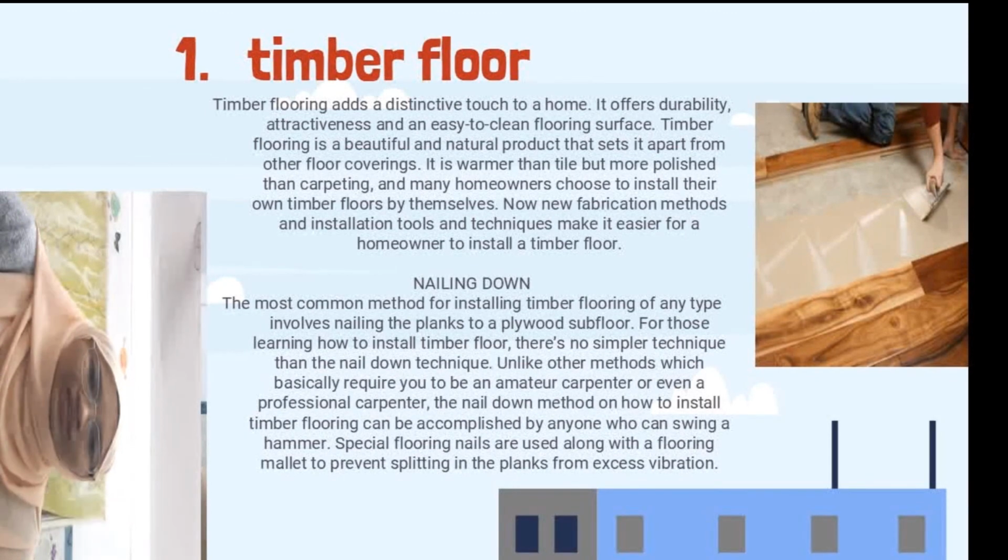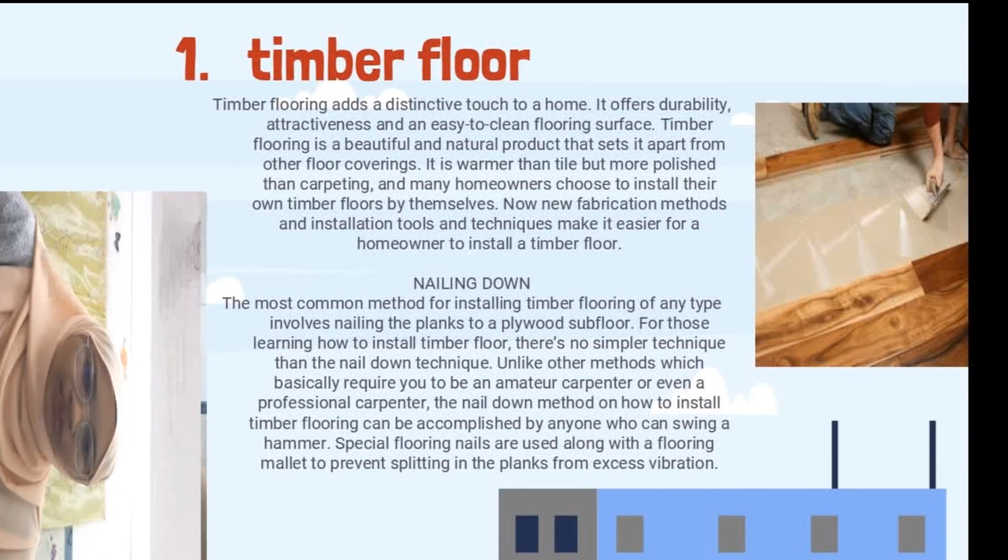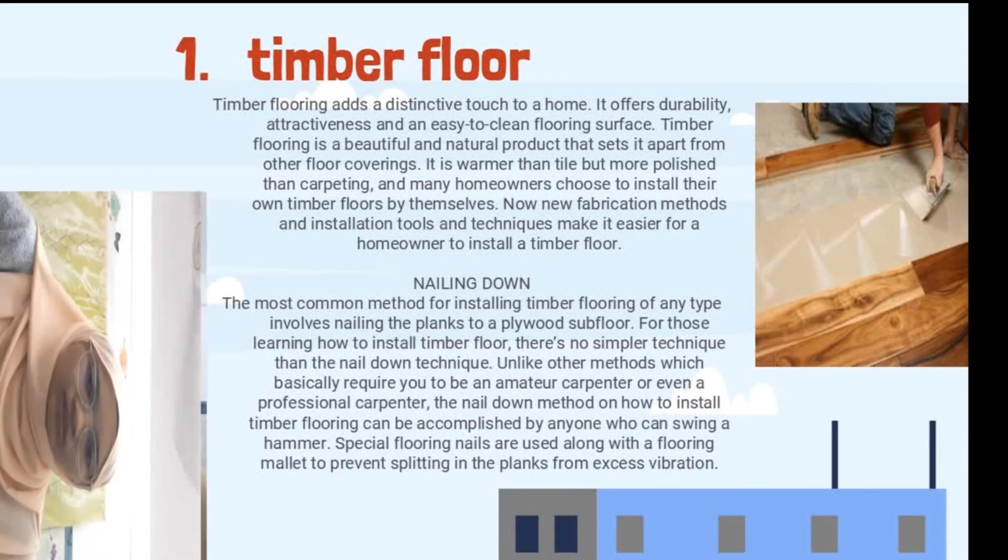First, we can do nailing down. The most common method for installing timber flooring of any type involves nailing the planks to a plywood subfloor. For those learning how to install timber floor, there's no simpler technique than the nail down technique.